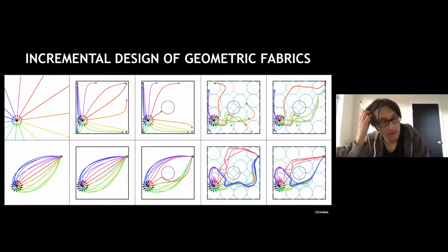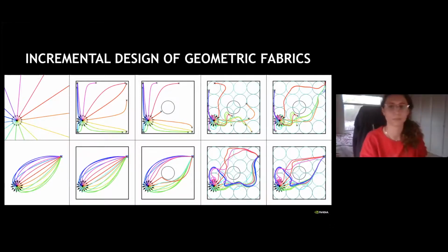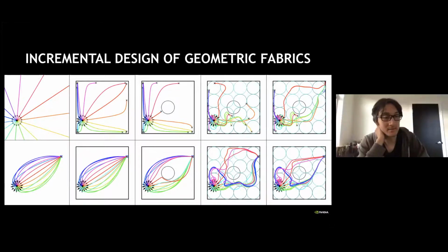Yeah. Those are good ways of designing stable systems. What we're focusing on here is a theory of systems that we can design by these nonlinear geometries. The focus is on being able to shape the behavior of this system using nonlinear geometry and use what are essentially classical Lyapunov principles to prove stability on top of it. Does that answer your question?